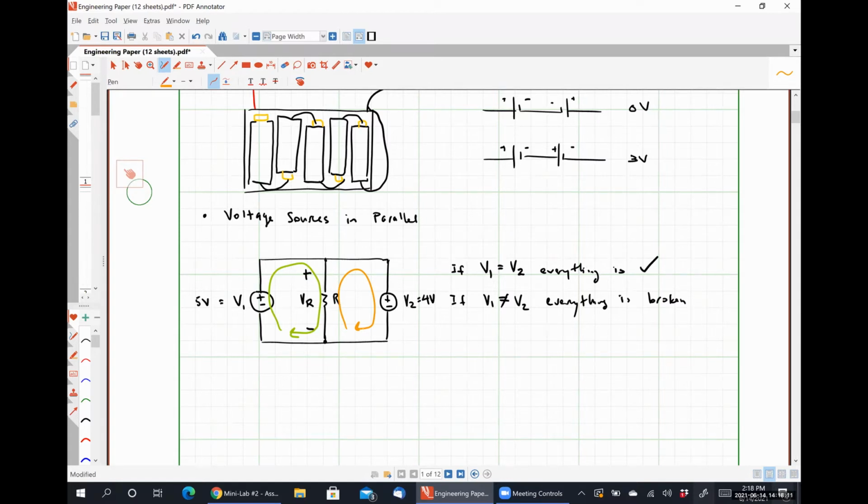Because effectively, if those wires touched each other inside your bag or whatever, you had 6 volts in parallel with 0 volts, and that causes a large amount of current, literally all the current that those batteries can supply, to pass through that wire that's shorting it out, trying to bring it up to a potential of 6 volts, causing everything to melt. So you can literally start fires by shorting out a battery.